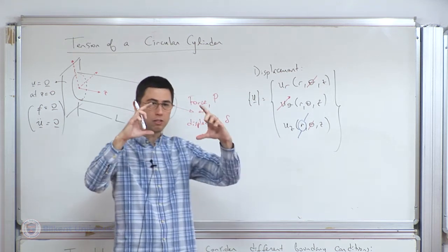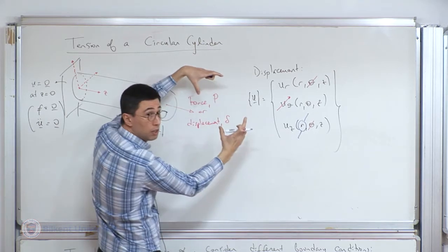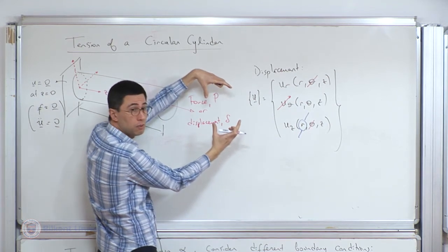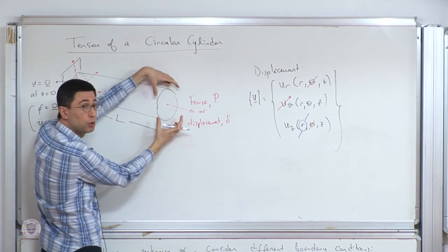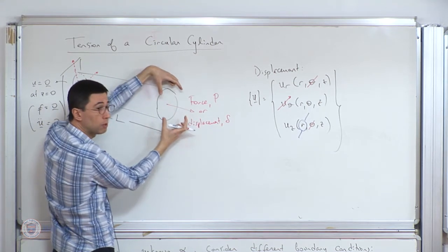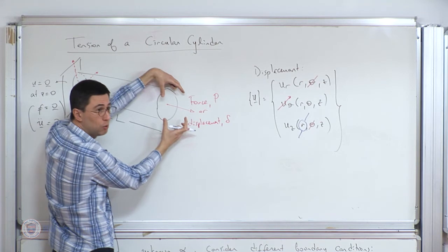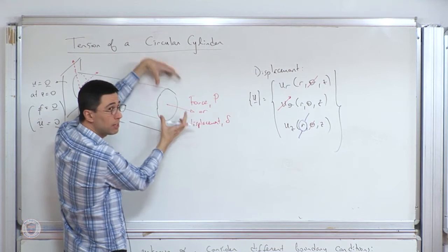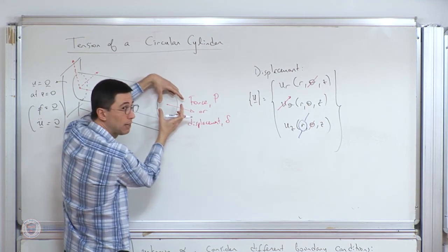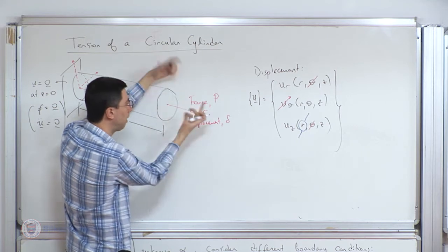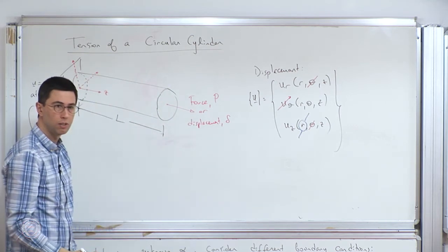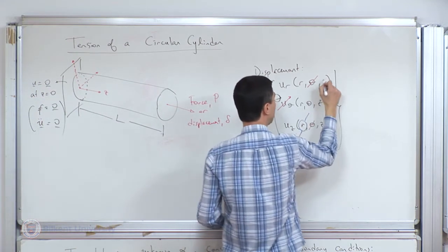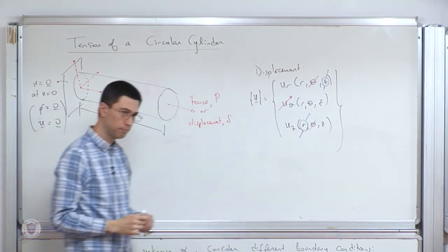What does U_R mean? So you look at the cylinder from the front with radial displacement. What should happen to the cross section? When I pull, should it get smaller or larger? You are assuming that the Poisson ratio is positive, which is plausible. It could be negative. If it's negative, it expands. If it's positive, it contracts. Does that amount of contraction depend on where I am along the cross section? It shouldn't, okay? But just like that, I want to cross out carefully, okay?